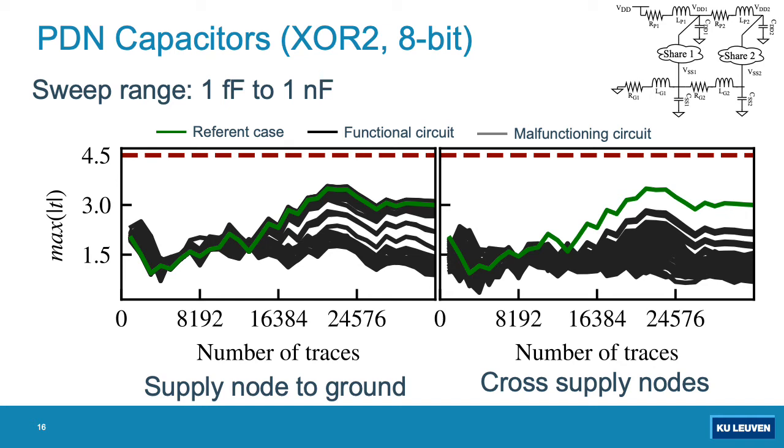As the name may suggest, the decoupling capacitors help the SCA security by effectively filtering the information carrying high-frequency supply current. Therefore, we see already at this point how back-end design techniques could be used to provide an additional security margin. So far so good, right? So these decoupling capacitors may actually help.